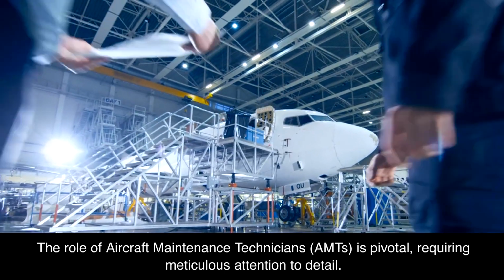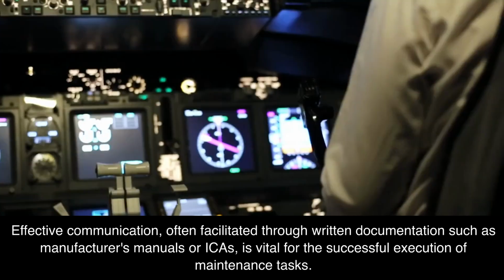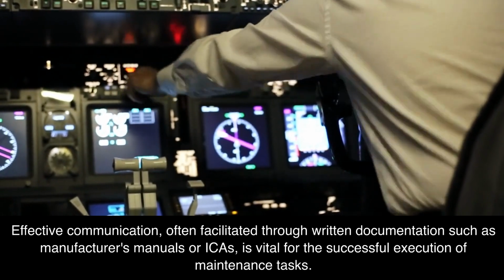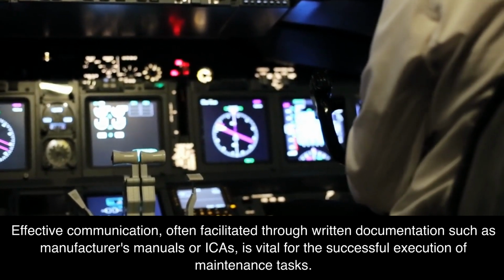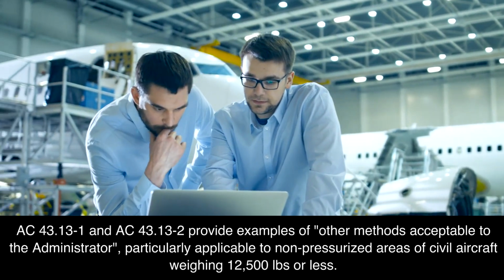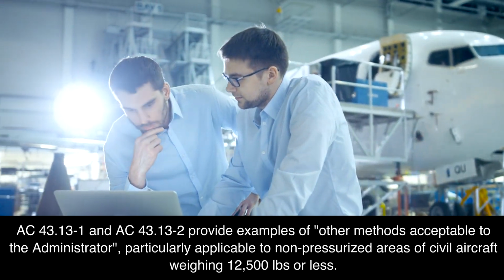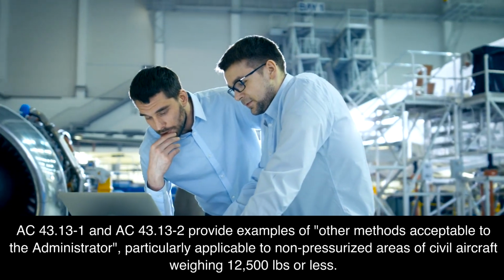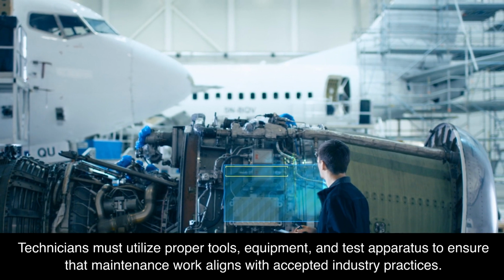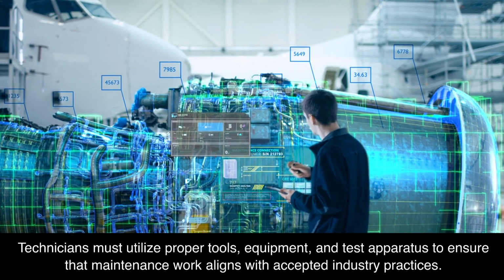The role of aircraft maintenance technicians, AMTs, is pivotal, requiring meticulous attention to detail. Effective communication, often facilitated through written documentation such as manufacturer's manuals or ICAs, is vital for the successful execution of maintenance tasks. AC 43.13-1 and AC 43.13-2 provide examples of other methods acceptable to the administrator, particularly applicable to non-pressurized areas of civil aircraft weighing 12,500 pounds or less. Technicians must utilize proper tools, equipment, and test apparatus to ensure that maintenance work aligns with accepted industry practices.